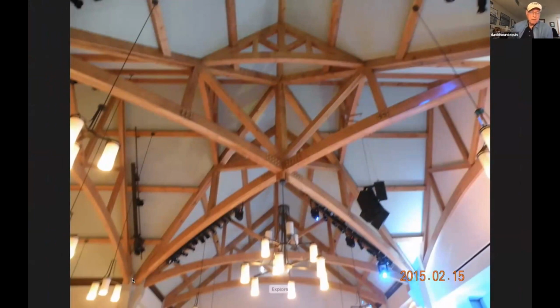Another thing, while I'm thinking about it, I want to mention, when you're dealing with glulams or any other curved member for that matter, but particularly for glulams, you have radial tension stresses here. As that member is under tension, it tries to straighten out. And when it tries to straighten out, the laminations of the glulam try to come apart. And so you always have to check these arch members that are under tension for radial tension.